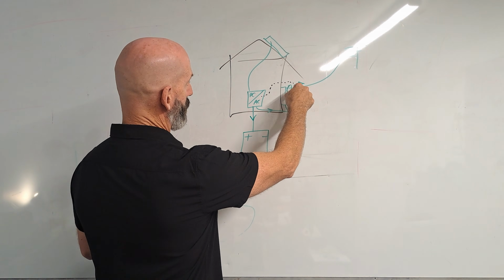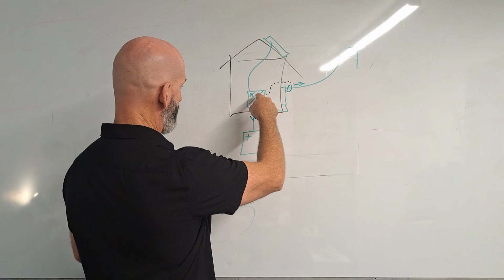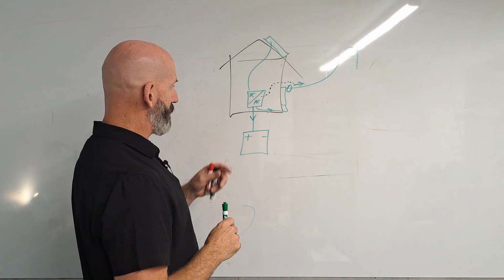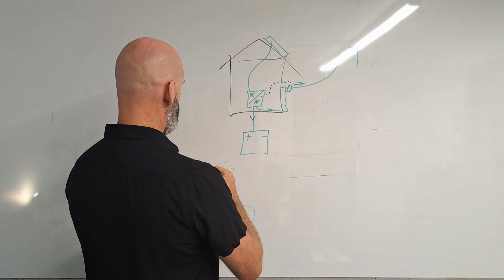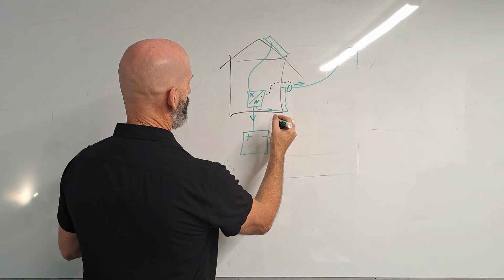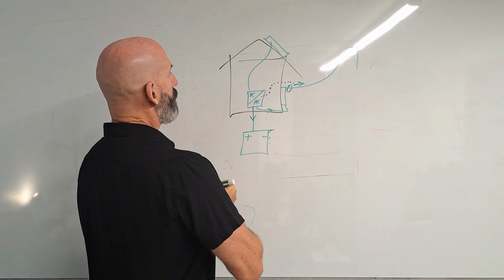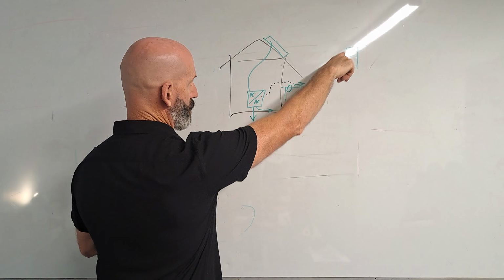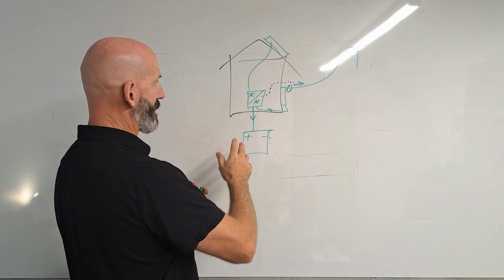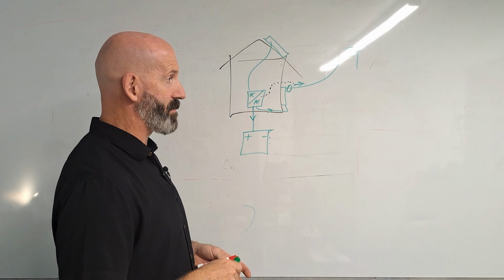And so that is going to monitor how much is going to the grid, and it's now going to divert that much power into your battery. Once your battery is full, all the way up to the top, then any excess that you produce will continue to go back like a normal Grid Connect system, and it will push the excess back out to the grid.